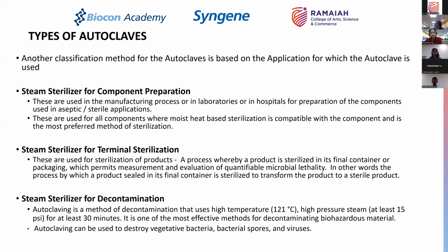The difference there is that when we come across the sterilization cycles or the controls that are required there, you are not looking at a sterility assurance. You're just ensuring that there is sufficient kill, so that your microorganism is not in a phase of growth, and it is either in a death phase or in a lag phase, so that you can dispose of it safely into a biomedical waste stream, or if it was a liquid, sometimes you even decontaminate liquid by heat, then you can send it to an effluent treatment plant where it gets broken down further.